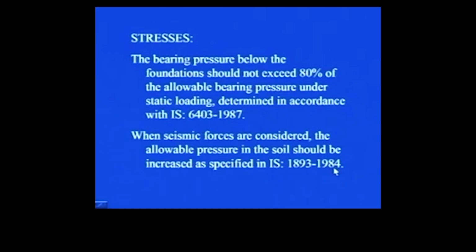So you know that these days, due to the scarcity of land, there are various sites which are quite seismic prone. So there we need to take these forces into account also, and we have to follow the IS code provisions. So in this particular lecture we discussed what exactly will be the behavior of a block foundation